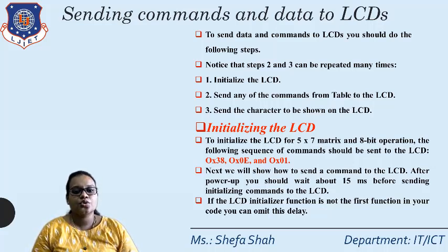Then next we will show how to send a command to the LCD. After power up, you should wait about 15 milliseconds. So we will generate a delay of 15 milliseconds before sending the initializing commands to the LCD. Right. So as we have said, the commands are instructions. So before giving these commands to the LCD, we will wait for 15 milliseconds, and after 15 milliseconds, we will give these commands to the LCD to initialize it. And if the LCD initialize function is not the first function in your code, you can omit this delay, right?